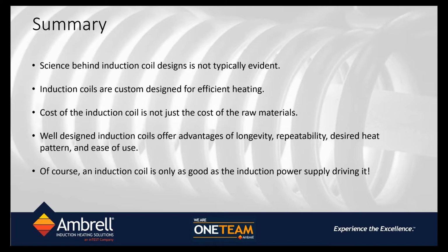Sometimes materials like titanium or graphite are used as fixturing devices, because the braze alloy does not stick to them. So if it is able to be used, you could use titanium rods or titanium push devices to hold the carbide in place. Because even though the titanium might heat from cycle to cycle because it's in contact with the metal, it will not stick to the braze alloy.